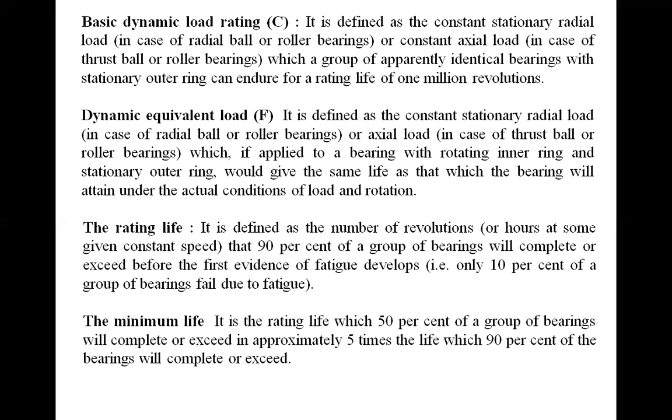So if I take 10 bearings and load them with axial and radial load, and 9 bearings complete 1 million revolutions or any rated life, that means only 10% failed. Out of 10, if one bearing fails, then we can say that that many revolutions is the rating life of the 10 bearings.